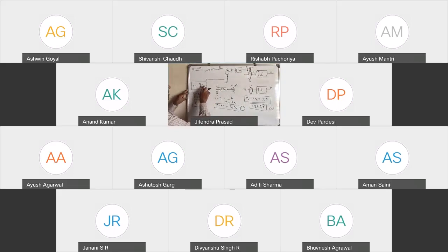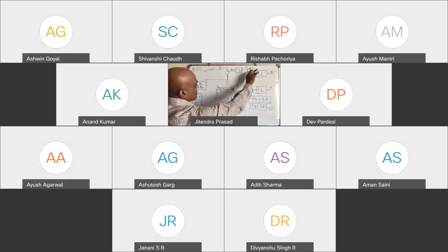So what is here? Let us say this one moves by theta m. So the distance traveled by this has to be equal to the distance traveled by this one, right? Because both are engaged. So you have theta m multiplied by r1 as the distance traveled, which should be equal to, for this also, theta times r2, right?